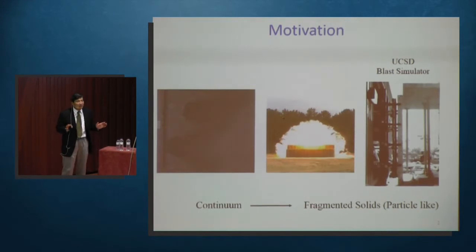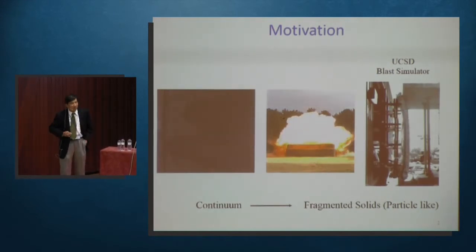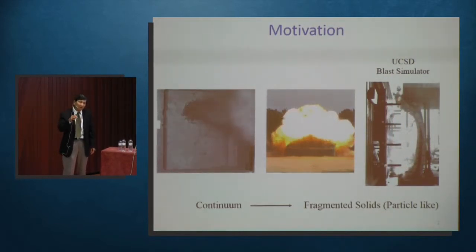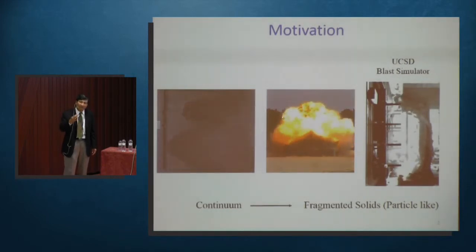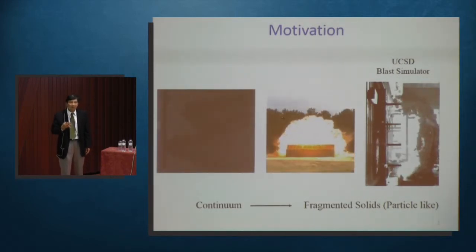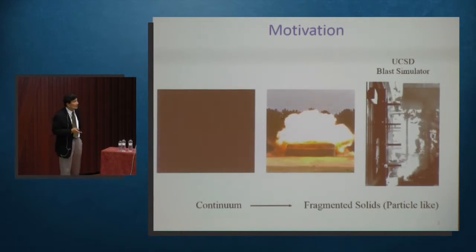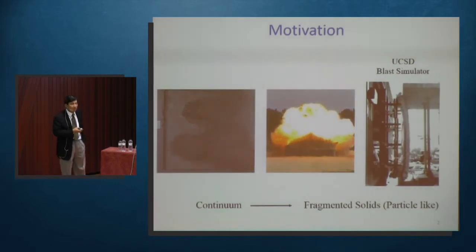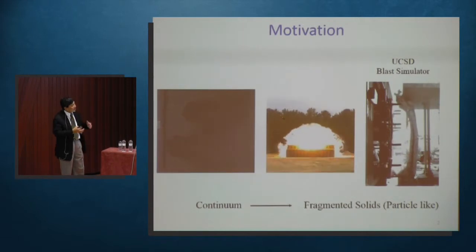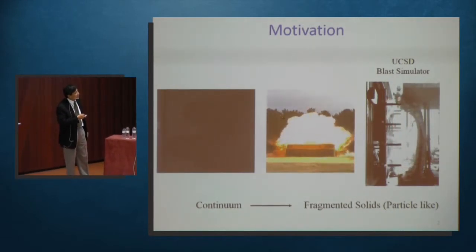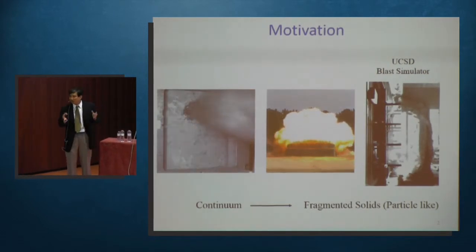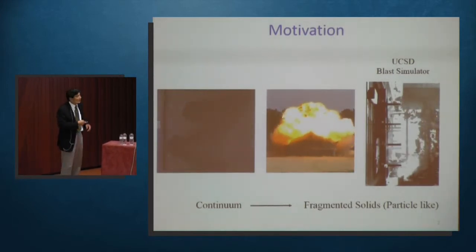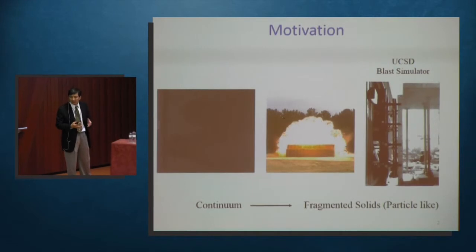Of course, a starting point of these problems is a continuum problem. Right? You start with the structure, and then there's an impact, a high velocity impact, and so there's an elastic response, inelastic, and then fracture and damage until the structural collapse. So to do this kind of computation, you have to start with a good solution accuracy of a continuum system. But later on, when damage initiates so much, it turns into fragmented solids, particle-like, not really at the level of particles that a lot of physicists are dealing with these days. But we're talking about fragmented solids that behave like particles.